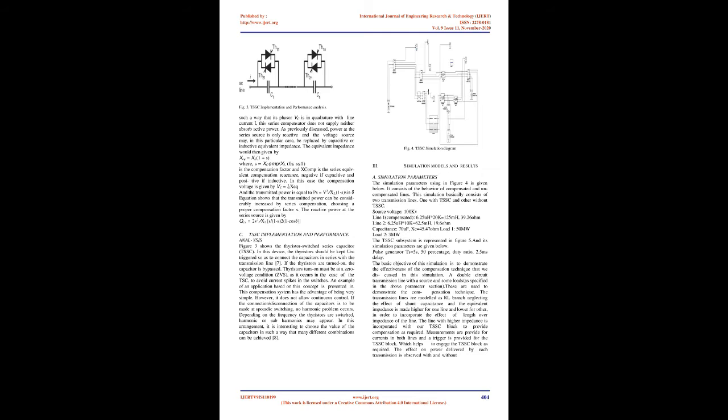In all applications the practical requirements, needs and benefits have to be considered carefully to justify the investment into a complex new device. The usage of lines for active power transmission should be ideally up to the thermal limits. Voltage and stability limits shall be shifted with the means of several different FACTS devices. It can be seen that with growing line length, the opportunity for FACTS devices gets more and more important.